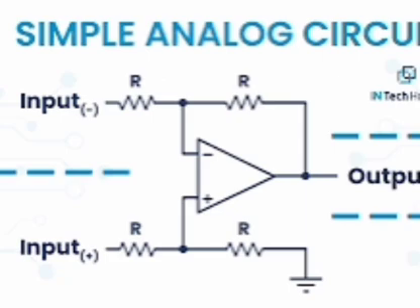Peak inverse voltage, all these come in the full wave rectifier. Peak inverse voltage for full wave rectifier center tap is PIV equal to 2VM. Transformer utilization factor TUF equal to 0.57 for full wave center tap.